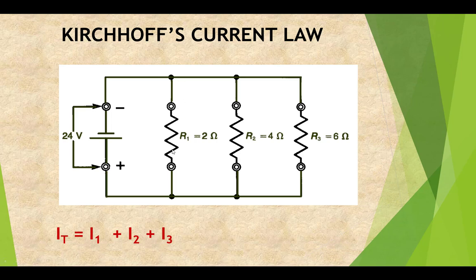So think about that. The smaller the resistance you have, the more current can flow. So that stands to reason that your larger resistance is going to restrict the current the most. Therefore, it'll get the least current.